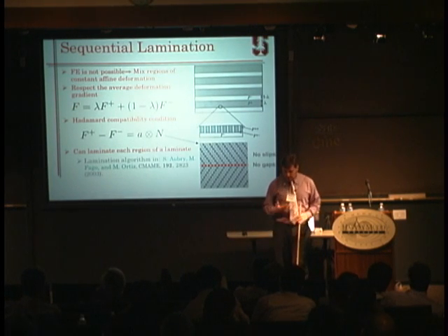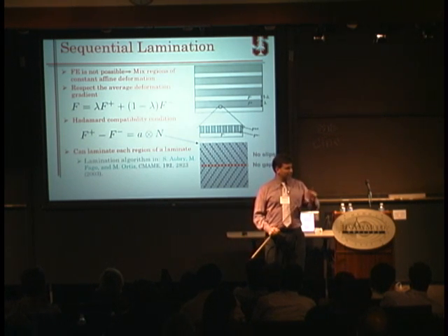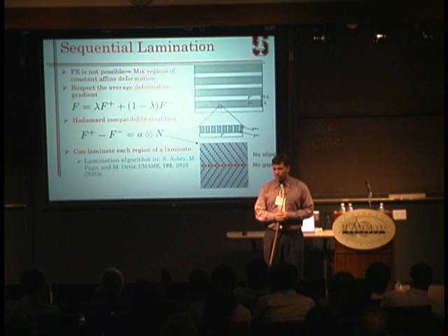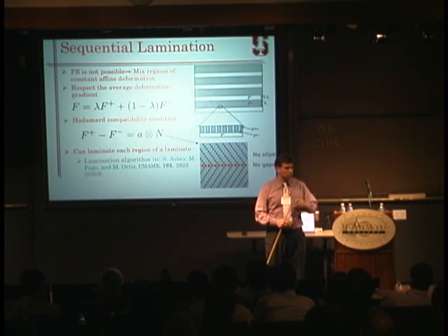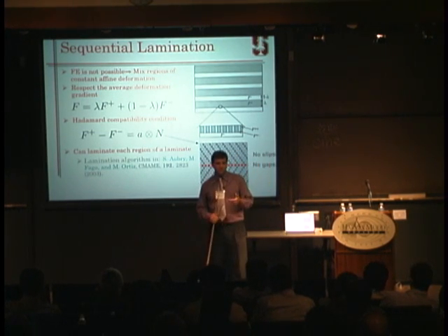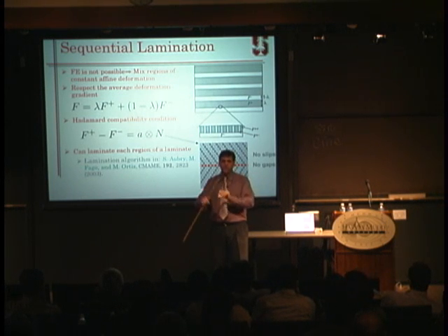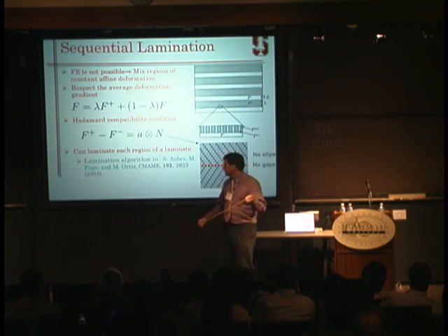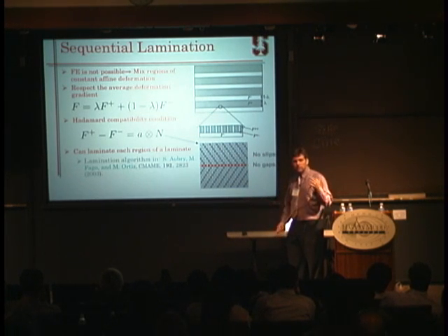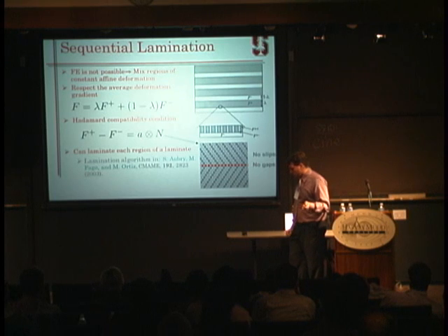So once you have this elastic energy density, you say, okay, now I know what to do. I just plug it into my finite element simulation package, I discretize my microscopic sample, and I try to solve it with discontinuous Galerkin, with whatever method you want. Well, if you do that, you'll get a solution that you may not understand. It will probably essentially oscillate from element to element. This is because sometimes there are no minimizers of this problem that are actual functions. Sometimes you get a measure as a minimizer of this problem. You have to enlarge the space in which you seek solutions.